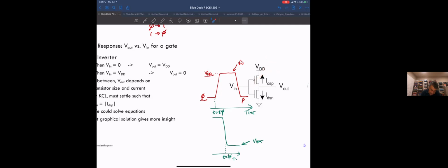We didn't really talk about the PMOS so much. Maybe we did a little bit in slide deck 5. We just said everything is inverted. But when this device gets a minus VDD VGS, it turns on. And the output is VDD. This device has been on for a while and has pulled this node to VDD. So the output is at VDD at this point.